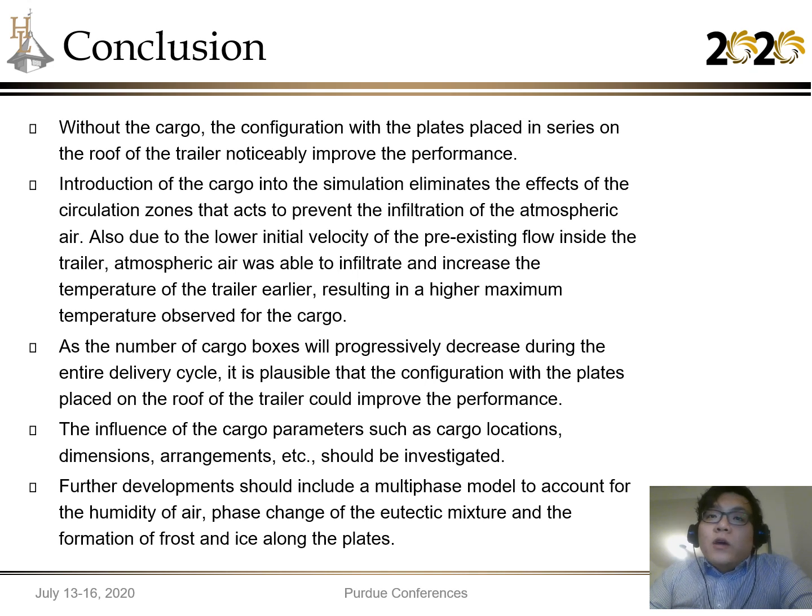So in conclusion, without the cargo, the configuration with the plates placed in series on the roof of the trailer noticeably improved the performance in terms of the renewal time and the infiltration rate due to the presence of the circulation zones and the cold air that surrounds the plates that is located near the top of the doorway where the infiltration occurs. However, introduction of cargo into the simulation eliminated the effects of the circulation zones that act to